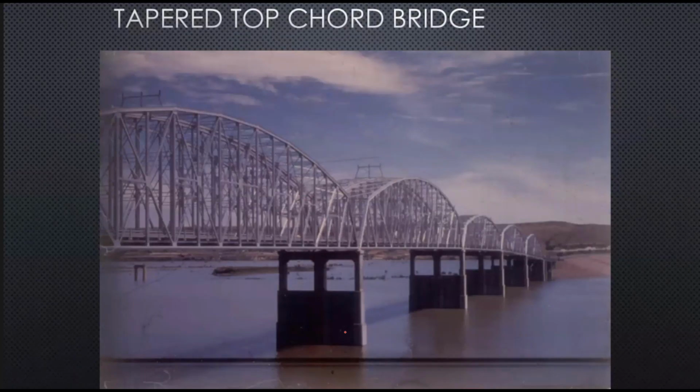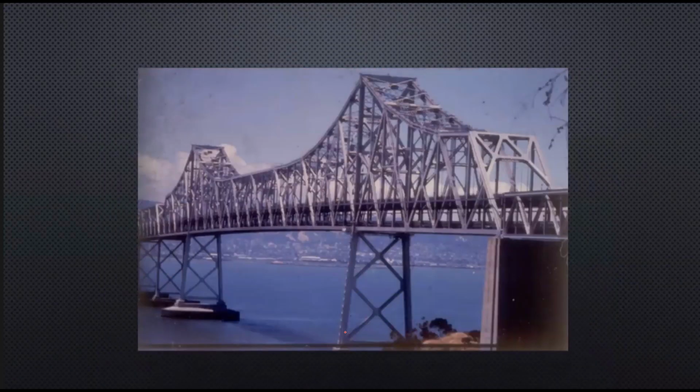This is a simple taper truss. It follows the simple bending moment. You will find the top chord members are high. All other web members are very thin, because it follows the shape of the bending moment, because in a simply supported span. What about here?